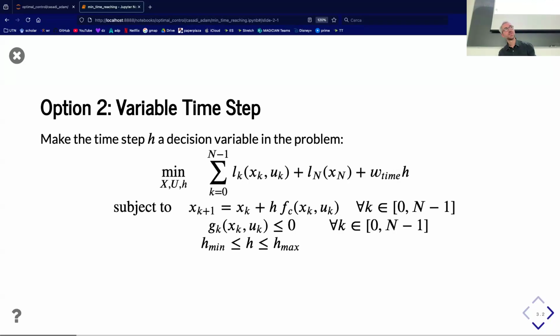And how can we dynamically set dt? I mean, isn't dt a parameter of a controller? Here we're not doing control. Here we are doing trajectory optimization. So now we're not in an MPC setting. Typically what you would do is first optimize the minimum time trajectory, and then you take this trajectory as your reference, and you might use an MPC controller for tracking it.